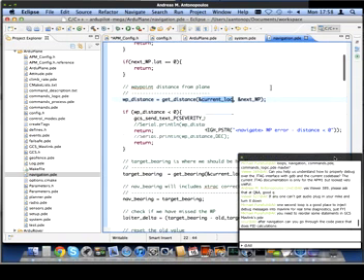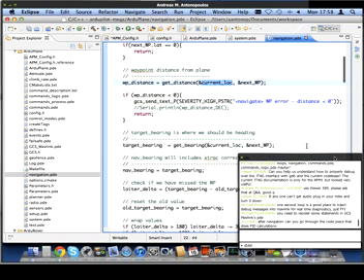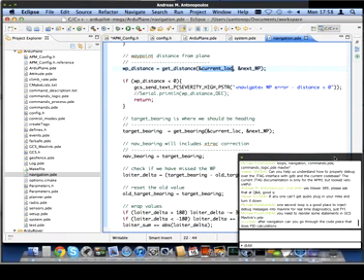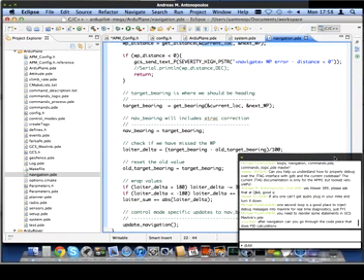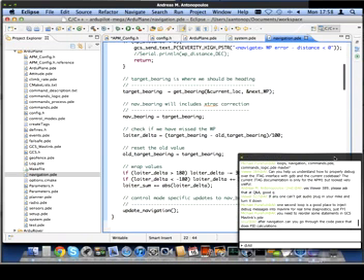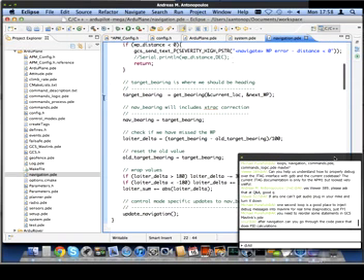And its output is the nav roll and the nav pitch. They're the two primary outputs. So the nav roll is the roll in centidegrees, hundredths of a degree, which is what roll the plane should try and achieve for the next tenth of a second. So this is called every tenth of a second, and it wants to know how much bank angle it should hold the plane at for the next tenth of a second. And it does this by